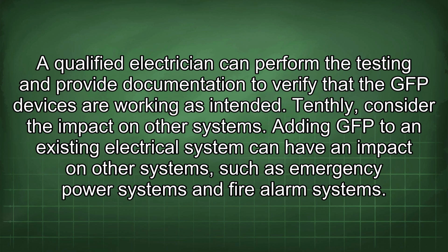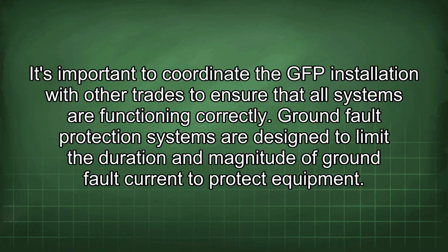Tenthly, consider the impact on other systems. Adding GFP to an existing electrical system can have an impact on other systems, such as emergency power systems and fire alarm systems. It's important to coordinate the GFP installation with other trades to ensure that all systems are functioning correctly.